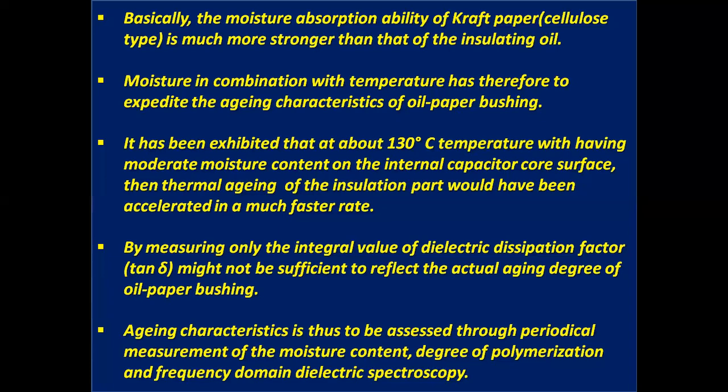Measuring only the integral value of dielectric dissipation factor, tan delta, might not be sufficient to reflect the actual aging degree of oil paper bushing. Aging characteristics is thus to be assessed through periodical measurement of the moisture content, degree of polymerization, and frequency domain dielectric spectroscopy.